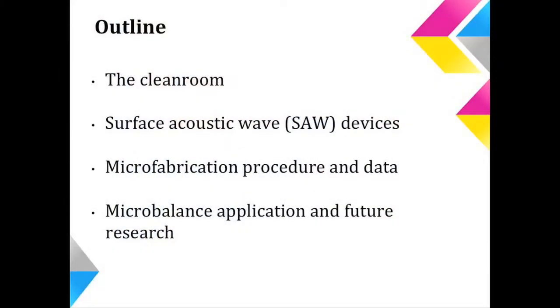Together we worked on fabricating surface acoustic wave devices in a clean room and applying these devices. So in this presentation, we're going to talk about the clean room and what it is, what we made in the clean room, surface acoustic wave devices, also known as SAW devices, the data we extracted from these devices, as well as an application with these devices as microbalances.